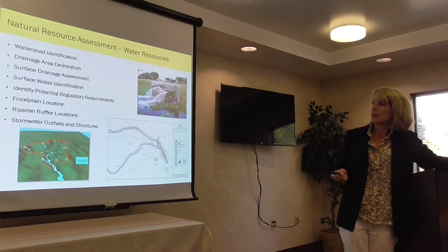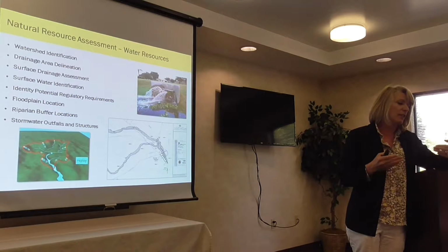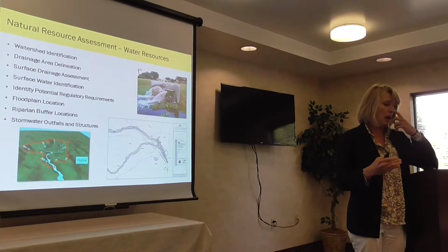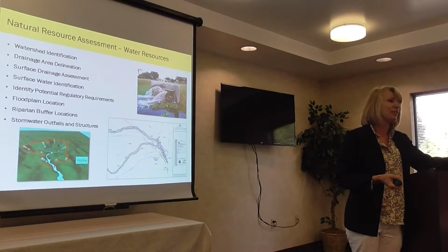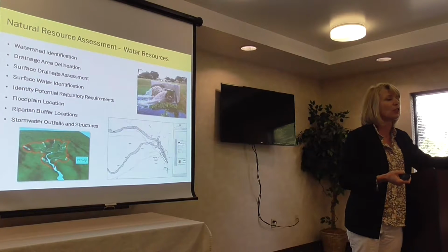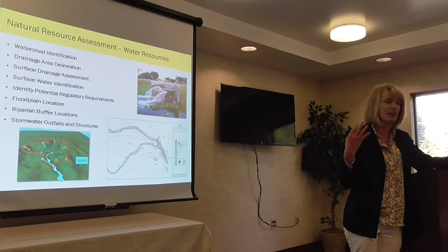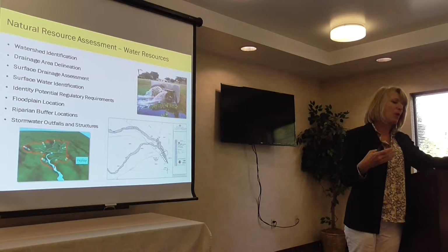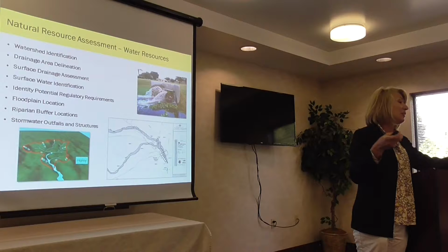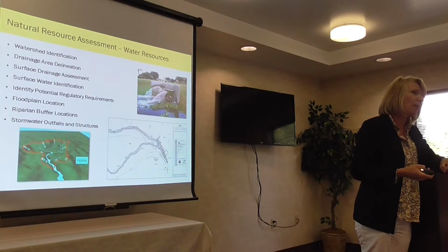Surface drainage assessment. It's really important to understand how the site is draining right now. And a lot of times that takes going out to the site and actually looking at it and making those determinations. One of the things that we found is, USGS and GIS, you can make assumptions with, but what you might think is where the drainage is coming from and what it's connected to may not be what it actually is until you get out there.